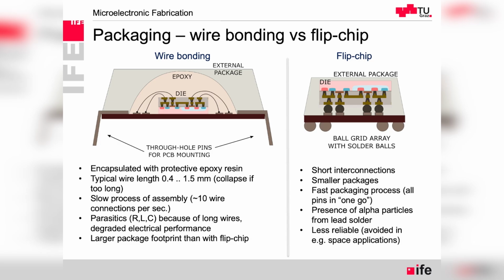One more thing that is unacceptable, for example, in automotive applications, is that these balls very often have some traces of lead, and this can cause alpha particle emissions. So they are more than likely to cause some single event effects, where a particle interacting with the electronics can cause transient currents, which cause soft failures or potentially even latch-up.